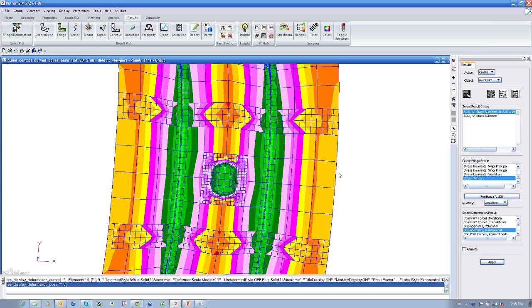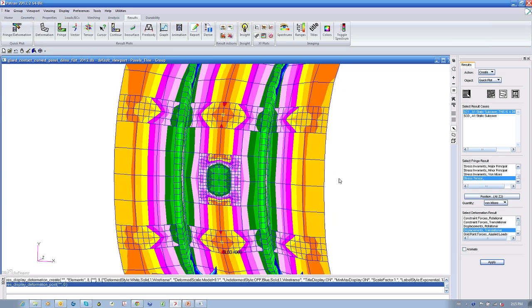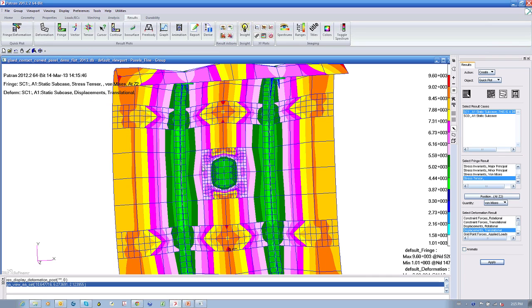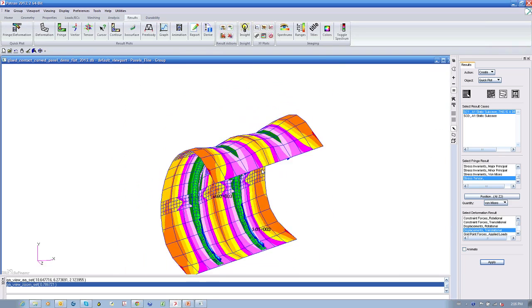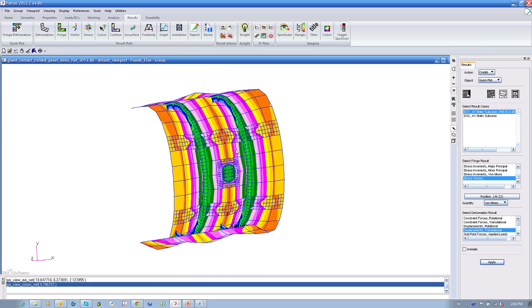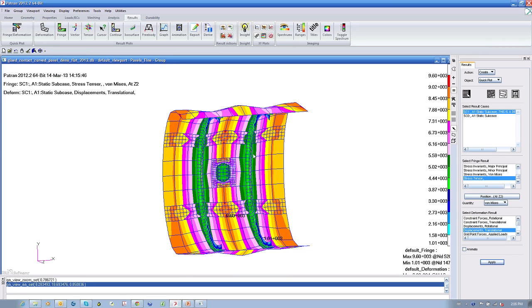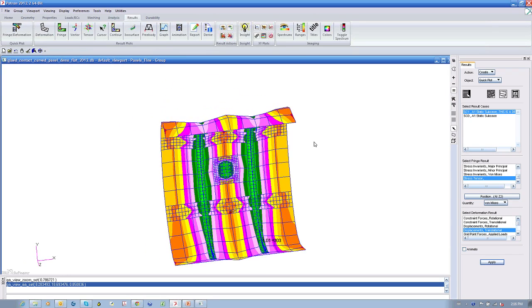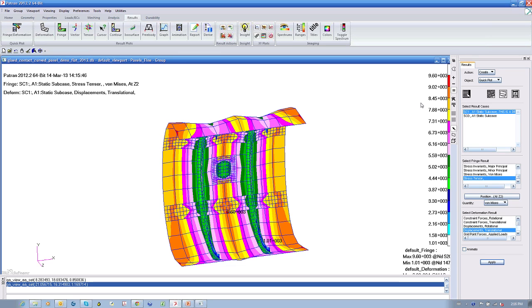Von Mises and an indication. You will see now that the von Mises stress, obviously those boundaries from coarse to fine are very narrow. So in order to look at the stress field in a very irregular manner, you'd have to maybe remesh a little bit differently to get away from the edge effect. But still, we have a fairly continuous field altogether. Yeah, it's like any boundary condition. If you put a singularity in some point in your model, you have to look at stresses and strain a little bit far away from it. Otherwise, you'll get affected by the proximity of that singularity.